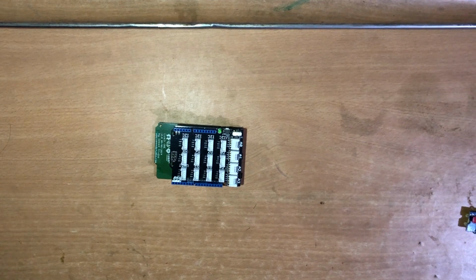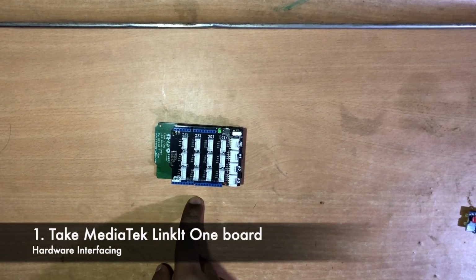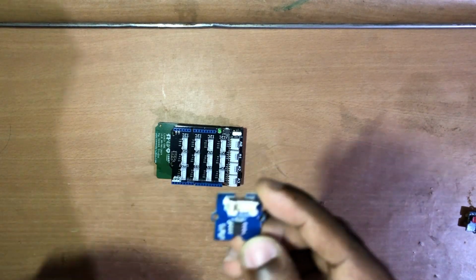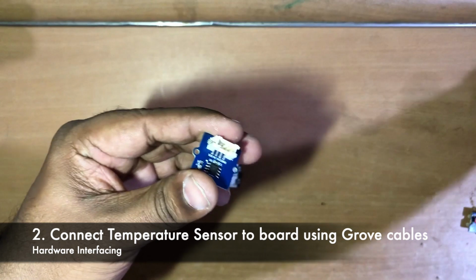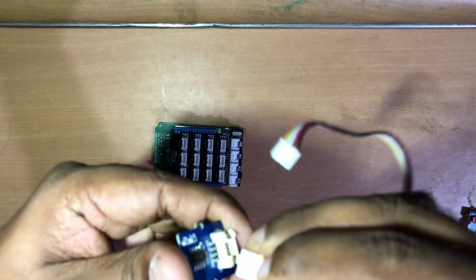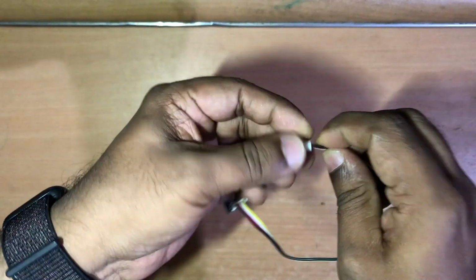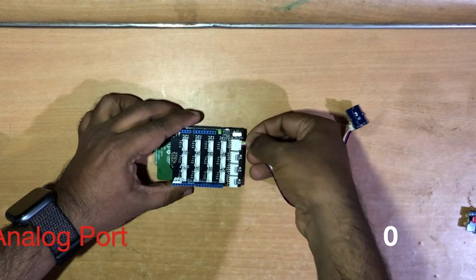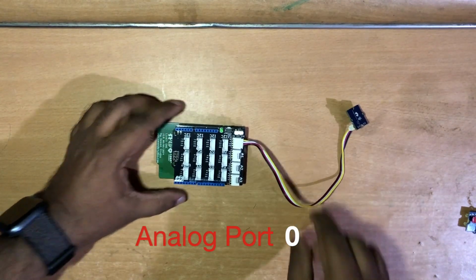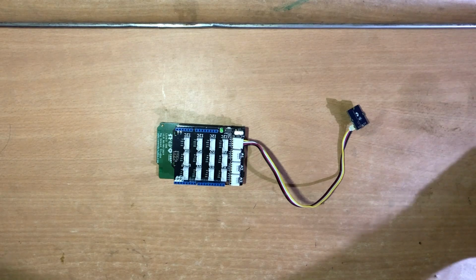Okay, so for hardware interfacing, we have a MediaTek LinkIt board with the Grove shield, and now this is the temperature sensor that we used in the last tutorial as well. So let's connect it first. We'll attach the Grove cable, and as we know, in the last exercise we connected to the A0 port. We'll keep it on the same port because we will just modify that existing program to display the temperature on the OLED.